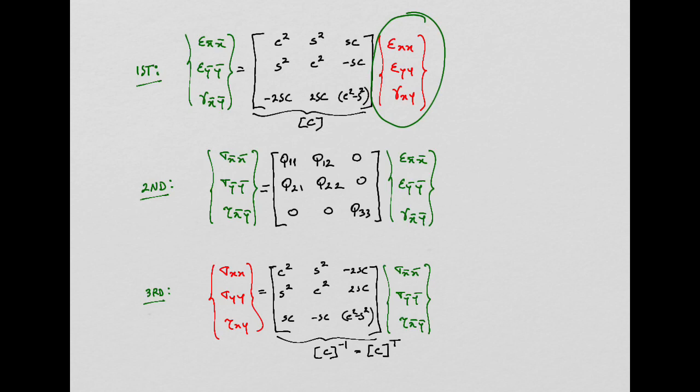But here in composites, we have to do this in these 3 steps. The reason is exactly the orientation of the fiber and the properties of the lamina, which change with the direction, which is not the case for an isotropic material.